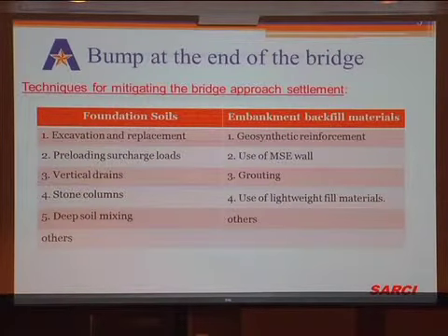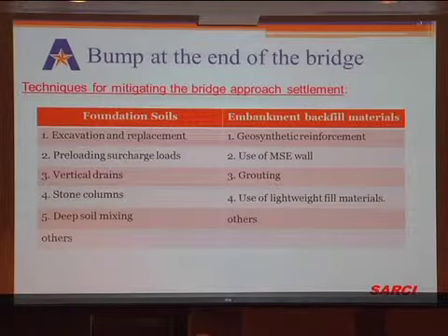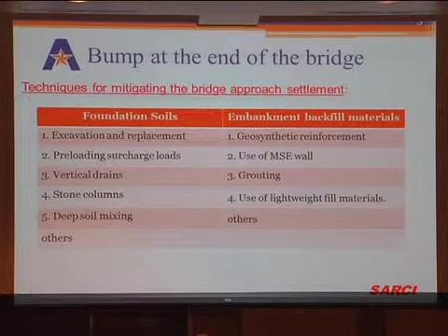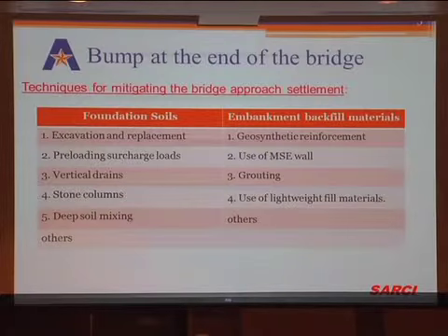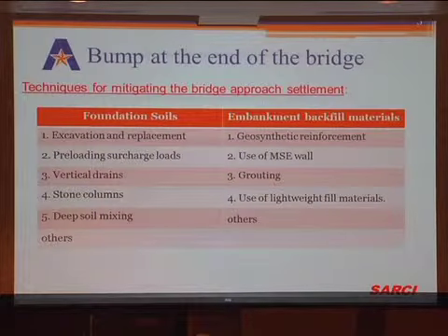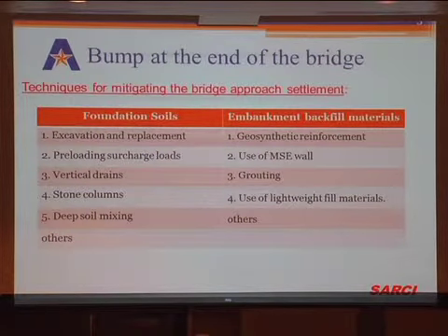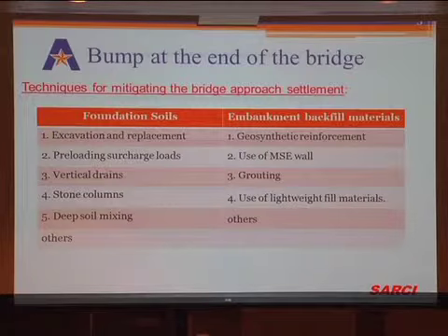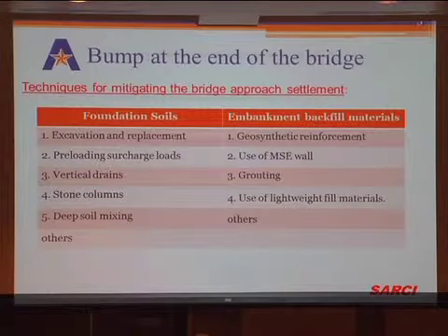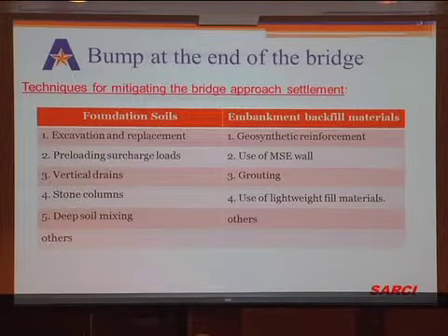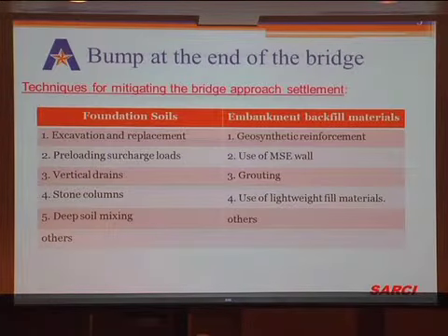And the other thing is deep mixing, which we use in our regular projects. Deep mixing is really a stabilization of native foundation soil that is weak and soft in nature, and we stabilize it with soil cement. In this particular one, we tried a lime cement application. Now looking at the other side, you have the embankment backfill material. There are a lot of studies going on at Federal Highway, mostly on geosynthetic reinforcement and segmental reinforced walls. That's been very popular. It actually came from Colorado DOT, and that's another one you can do. And you can also use some MSE wall types.